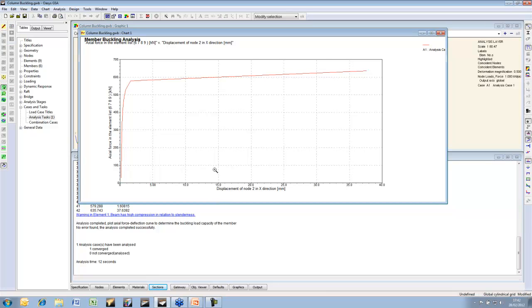And remember the modal buckling capacity was about 640, and if I ask for the nearest point, you see this, we get a maximum buckling load of 635 on this chart, with not so much detail on the last bit where it goes quite suddenly, but from this chart you can sort of work back to a safe working load where the displacements are not excessive.